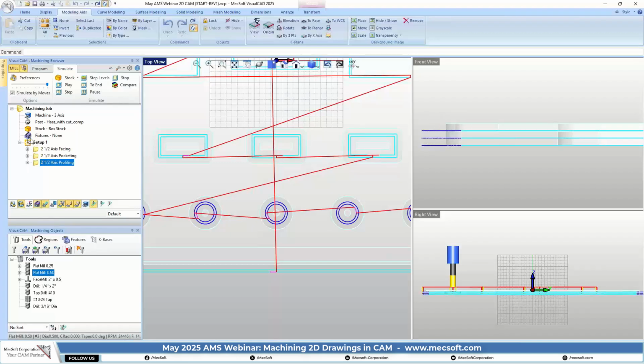If you remember, we actually didn't create a work 0. You don't have to have a work 0, but by default it's at the top of your stock. And we entered a negative number, which brought it down to this point right here. Okay, and then our cut depths went from this level on down. We used 3 cut levels. Okay, so let's turn this off.